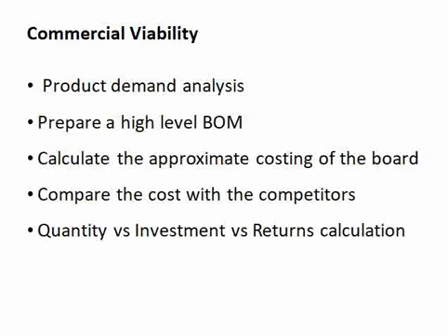We are going to do a market study. Initially, the marketing team would have done it, but again, to calculate the commercial viability, we are going to dig deeper, and then we are going to prepare a high level BOM, bill of materials, and then calculate the approximate costing of the board, and we are going to compare this cost with the competitors.